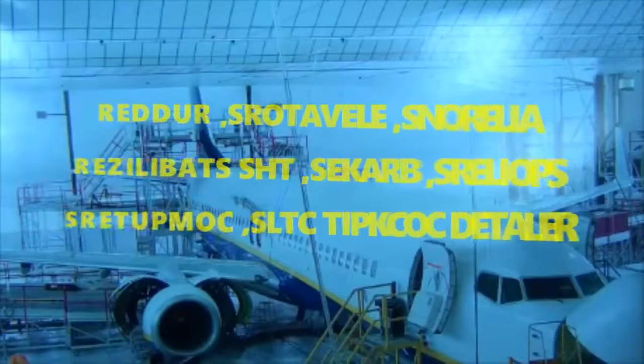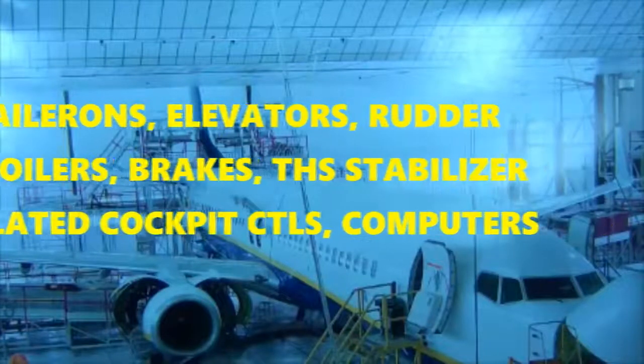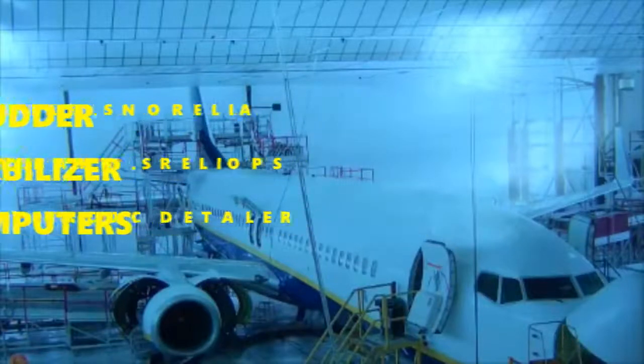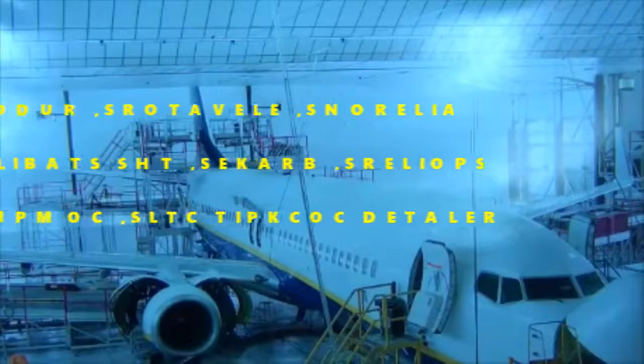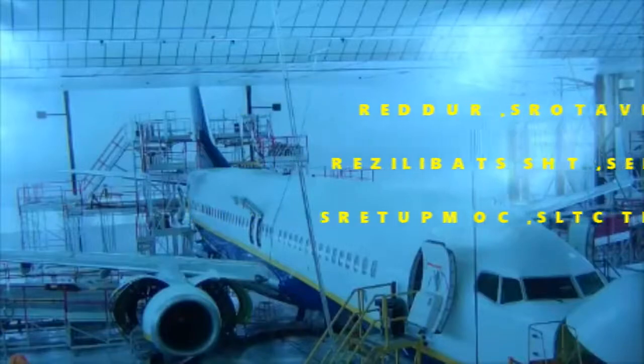So when we talk about flight control system, what is it? What that's encompassing is all the control surfaces except for the slats and flaps. So that would be your ailerons, your elevators, rudder, spoiler, your trimmable horizontal stabilizer, and also all the computers that are related to controlling those control surfaces. It also includes your speed brakes and your ground spoilers. So all spoilers, whether they're operating as flight spoilers or ground spoilers.